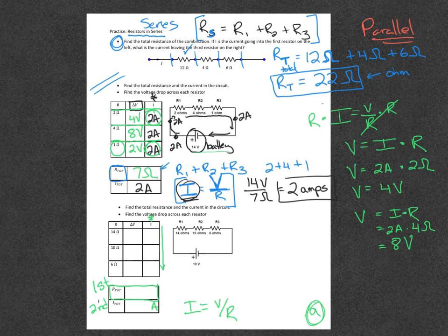And then step 4, let's use this new form of Ohm's law. See how we learned it over here? We divided both sides by R, V equals I times R, and you stay within your row and calculate the voltage of each resistor by multiplying I times R.